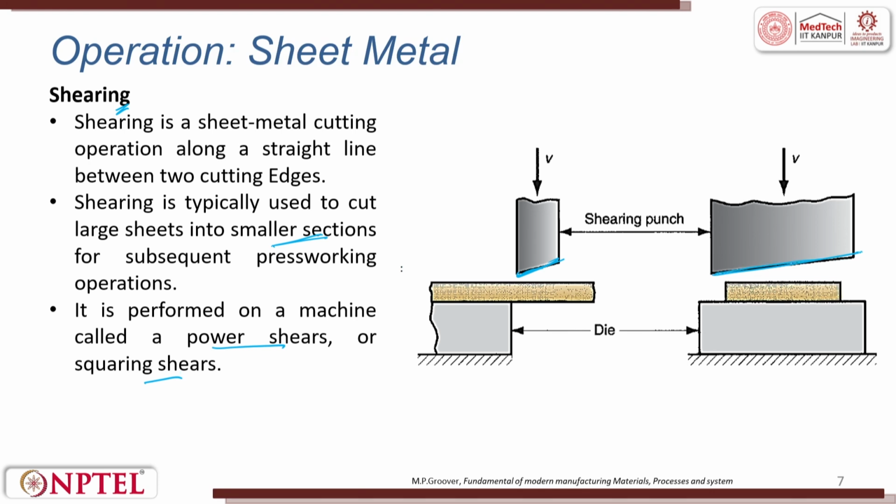This is always tapered. Why is it tapered? Because we always start at one edge, called the first approach edge. At the first approach edge, you have a sharp corner, and if you see the stress generated, it is force per unit area. The area is very small, so for whatever normal force, the stress will be very high.